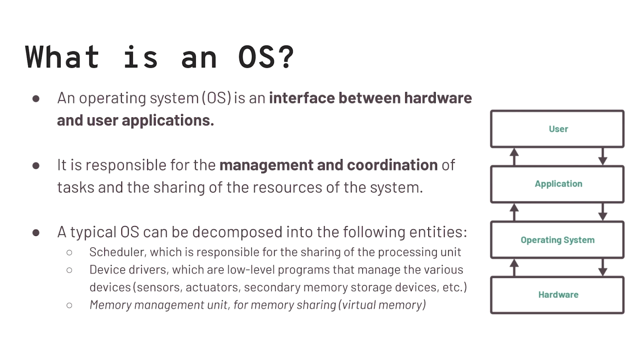And two more things that are not so relevant in the OT world are memory management, since virtual memory may not exist in the OT world because there's no multi-user environment, so there's no need for virtual memory; and the same thing with graphical user interfaces. You don't need a GUI at the OS level. You may have your HMIs, but that's at the software level. It's different, and you typically create it through connections to the PLC.